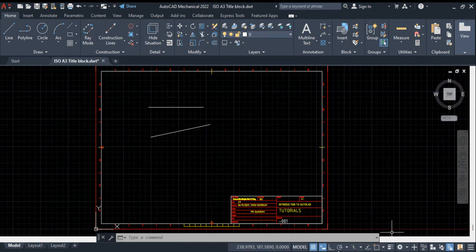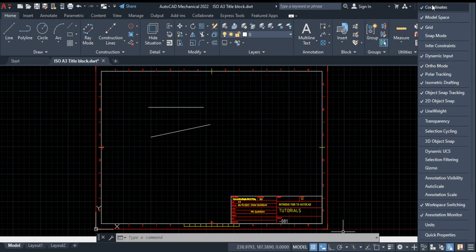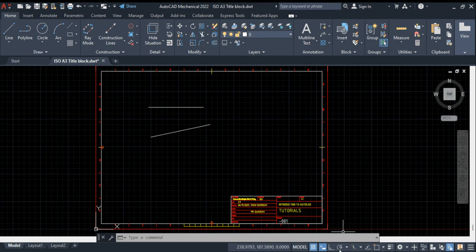So basically these tools or these commands here kind of have a constraint on your drawing area. Once you begin to initiate a particular command, they begin to affect how it's being used. So we now know the dynamic input, we know the auto mode. Now let's look at a very important tool as well called the polar tracking. So before that, make sure you go to the customization menu, make sure that you have polar tracking checked. So once you have it checked, let's activate it here. So I click on the polar tracker. It's like a circle with two lines meeting at the center.